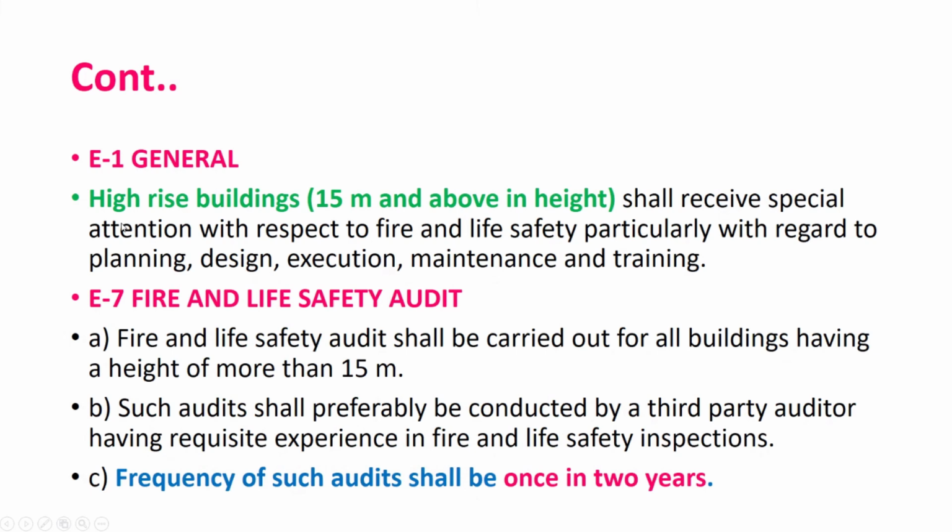Similarly, you should also prepare the wastewater and open surface plan. How the rainwater will come, how the open drains will be there, what should be the slope of that open drain, at which particular location they will be connected, and how it will be discharged to the outside requirement. We can now understand how many types of plans are required to be made.